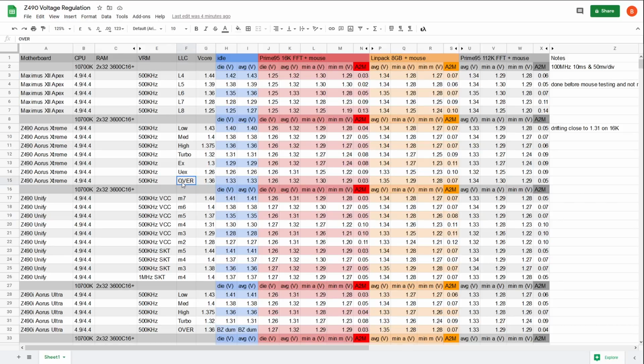So yeah, override mode's really cool. You do need to use an up-to-date BIOS. There are certain BIOS versions where override mode is horribly broken. You'll know it's broken because you'll get hit with 1.55 volts when you try to use it, and in that case, don't use it. But make sure you're on a BIOS where override mode actually works, and then override mode is amazing.